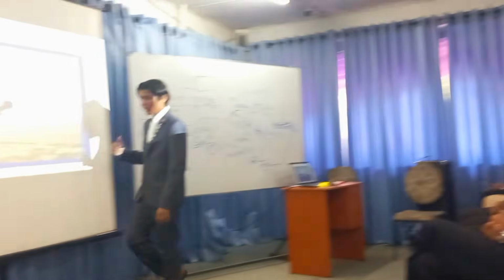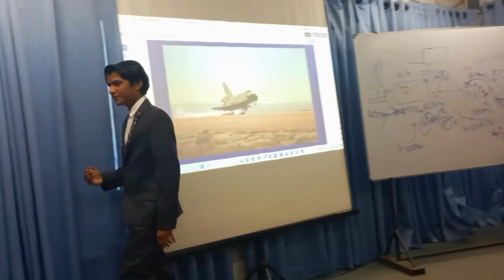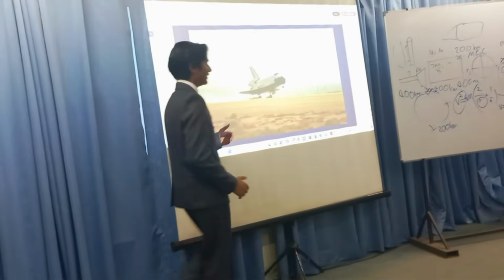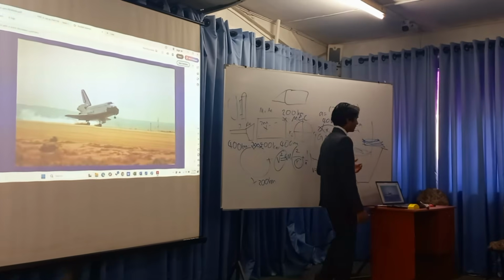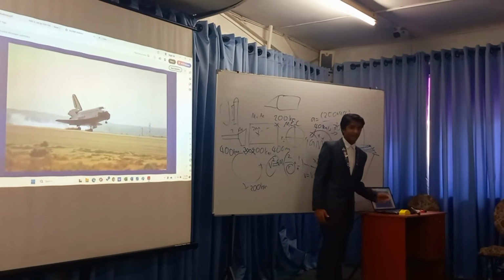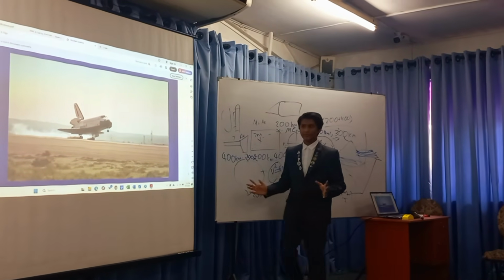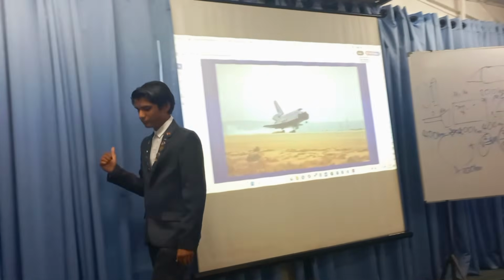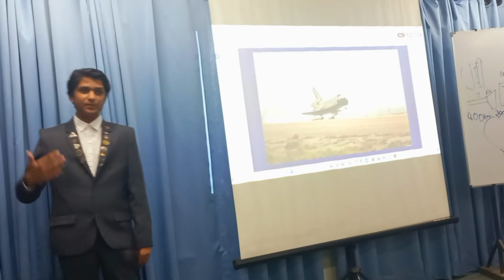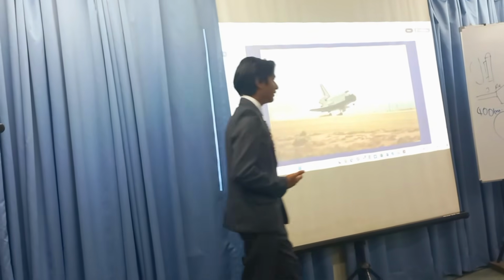Well, what happened on United Airlines 232 was it tried to regain control by using one engine after the other. It failed. That was mostly because the elevator systems were so damaged and the aileron systems were so damaged that the complete hydraulic system of the aircraft was lost. They could not control anything. If this happened to something like the space shuttle during landing, during descent, if they lost complete hydraulic control, they could rely on the RCS.